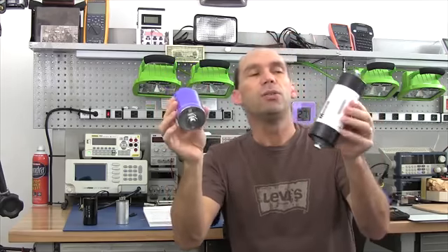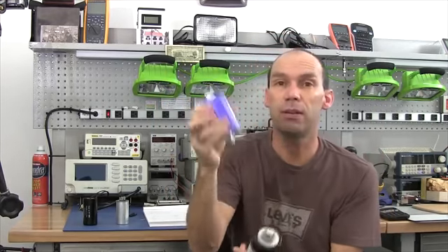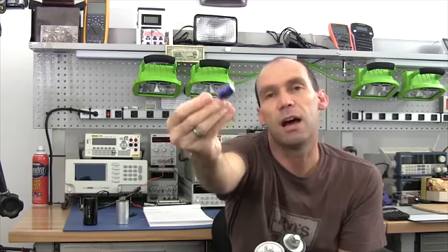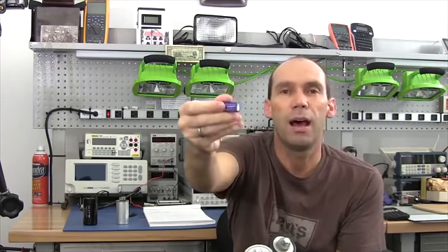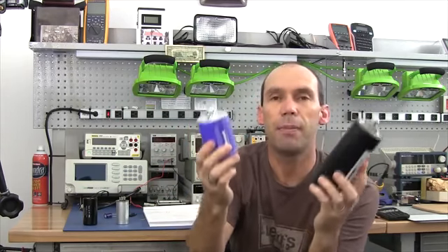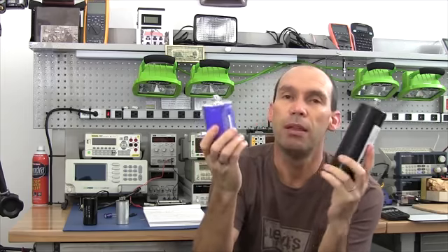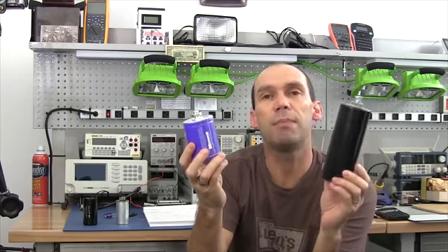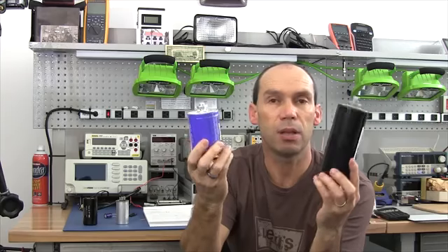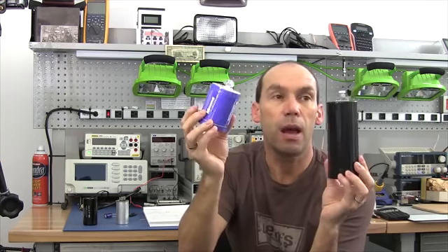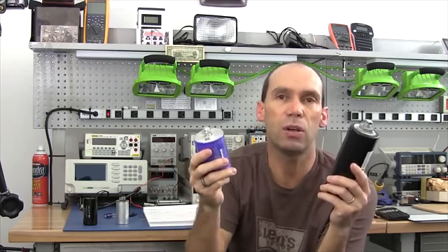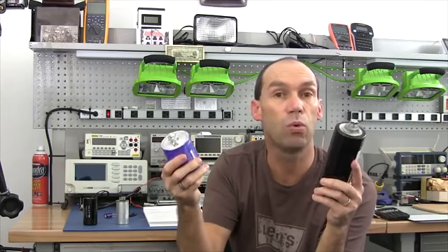But going back to super or hybrid capacitors, now these come in various sizes. I have ones which look the same size as, let's say, an electrolytic like this, and I've started experimenting with running devices off these. Now the future for supercapacitors and hybrid capacitors is potentially very interesting, because even today they can be used in hybrid vehicles. They use them in particular in the regenerative braking system, so that when vehicles are braking, they apply energy into these, and then that energy is used, let's say, to accelerate the car to start it, to preserve either the main batteries or fuel.